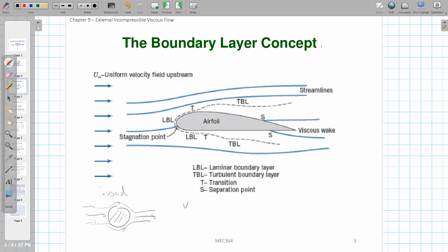But if the flow is viscous, and you also have the flow over the cylinder, what does the streamline look like? The flow pattern will totally change. It will become something like this, and you have wakes here, wakes here, wakes here. So this is an example I want to show you that with the viscous effect, the flow pattern will look very different. This is for the inviscid, this is for the viscous.